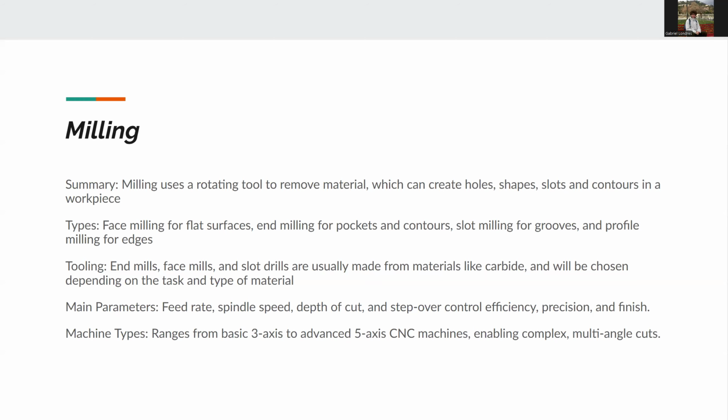Different types of milling. Face milling is for flat surfaces. End milling is for pockets and/or contours. Slot milling is for grooves, and profile milling for edges.